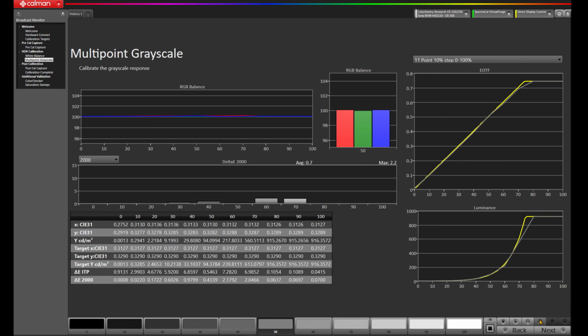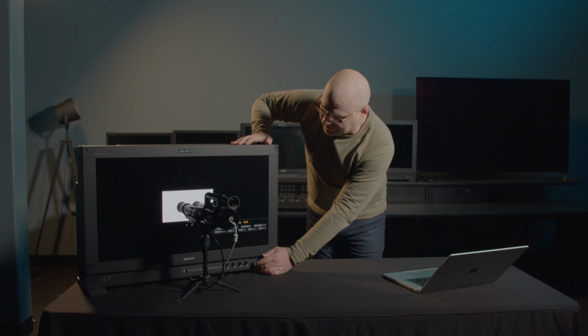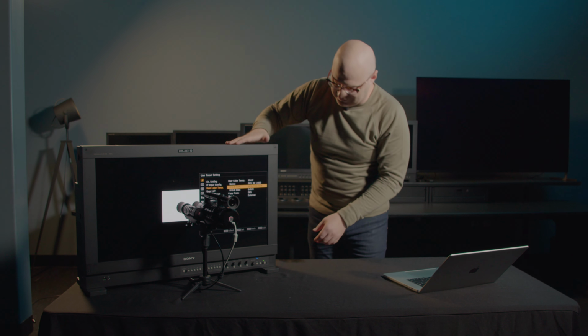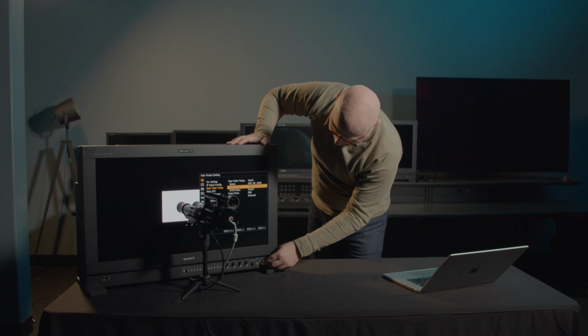Okay, so we're at 94.0, our target's 94.378. Maybe go just a couple more. Remember, there is going to be some fluctuation in the meter and the repeatability and the stability of the system. Not to mention, we also have some very bright lights in the room shining to make this video. That could also be contaminating the readings a little bit.